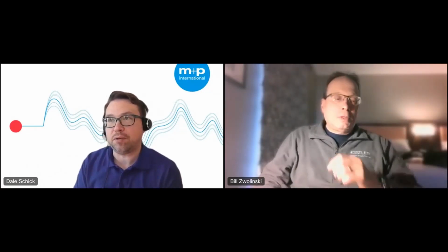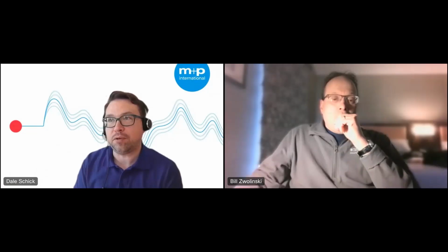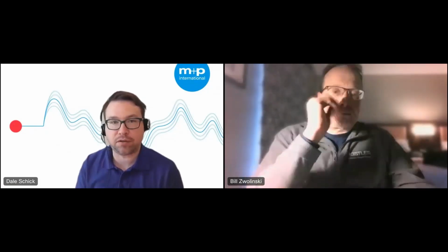It's a very small fixture, but also it is stiff enough. Both the fixture and the expander head were tested, and their resonances are well above 3 kilohertz. So if we're only testing to 2000 hertz for the sine test, we don't start to see that fixture resonance creep in until maybe 2200 hertz or so. So we did plan for that, and I think that's the key in that type of placement.